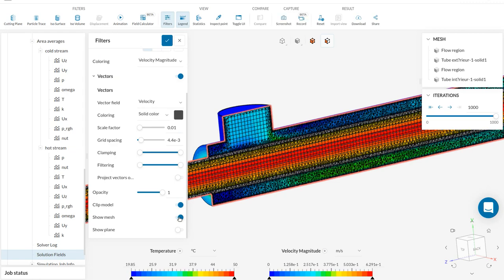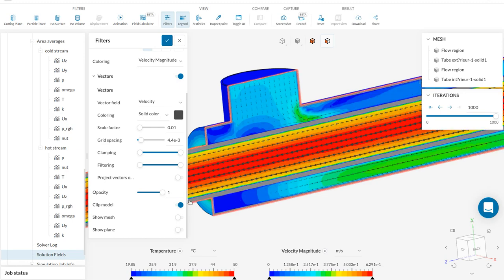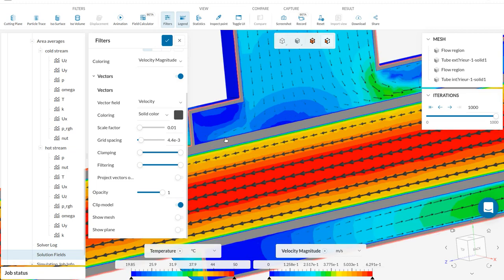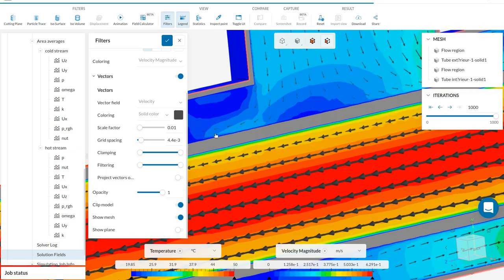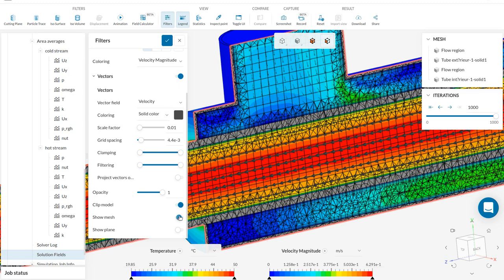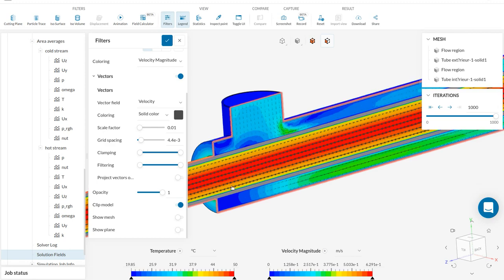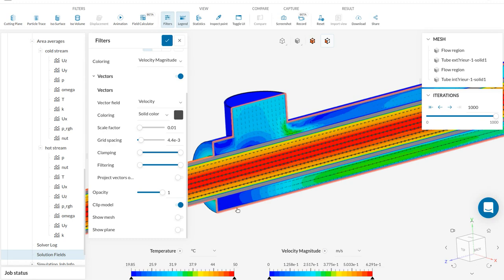I did not pay any attention to the mesh, but it is highly recommended to pay attention to the layer sizes and also perform a mesh independence study to achieve realistic results. Because running a successful CFD simulation does not mean that the result is correct. You need to ensure that results are independent of the mesh size.